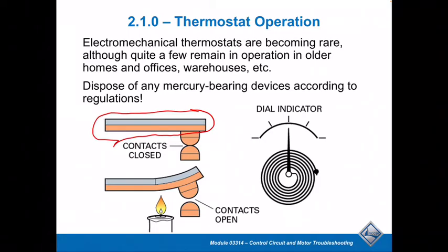On the mechanical side, where you might be dealing with the bimetal type sensors as opposed to thermistors, there are 2 different types that you might see. One might be like that bimetal bar you're seeing on the left side of the image, whereas probably more common would be the spiral wound.